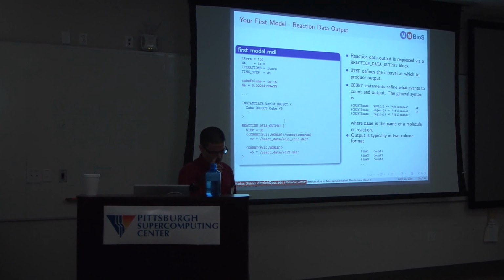Also keep in mind that if you want to do this sampling, you have to actually specify different random number seeds. If you just run MCell 1,000 times, you get 1,000 times exactly the same simulation. That is sort of a pitfall. So if you need to sample, pick different random number seeds: seed number 1, 2, 3, 4, 5, however many you need to go. Then you get statistically independent simulations, and then you can do your statistical analysis. If you just keep running MCell 1,000 times, you don't get any averaging really.